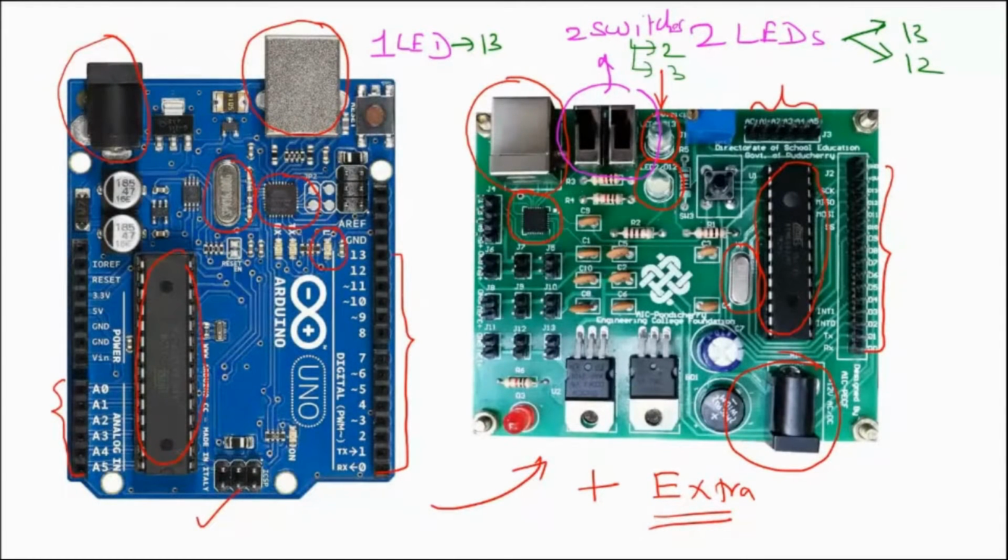This board also has an onboard potentiometer for giving analog input. You can simulate an analog input by using this onboard potentiometer. This board doesn't have any onboard potentiometer. And this is with regard to input and output. With regard to output, this one has the option for 3.3 volt and 5 volt. So you have one 3.3 volt line available here and one 5 volt line available here.